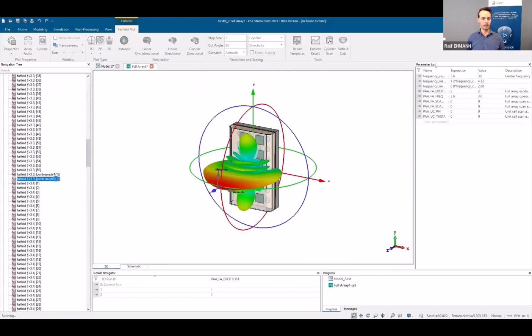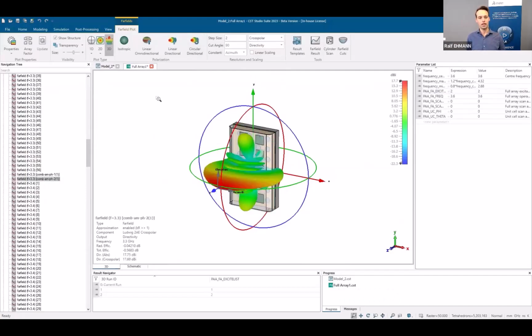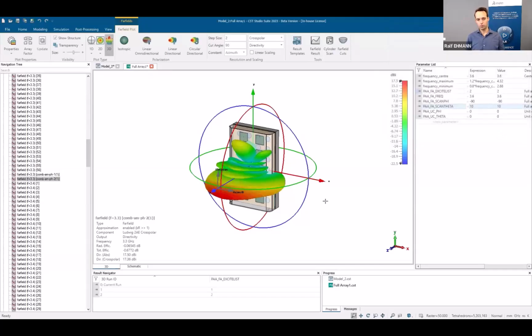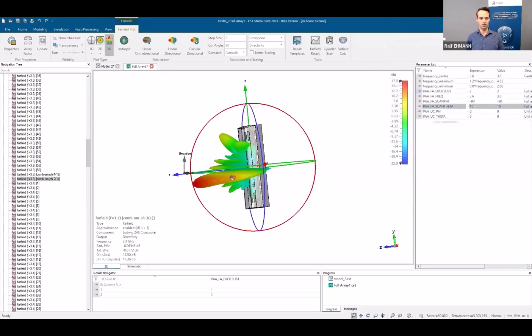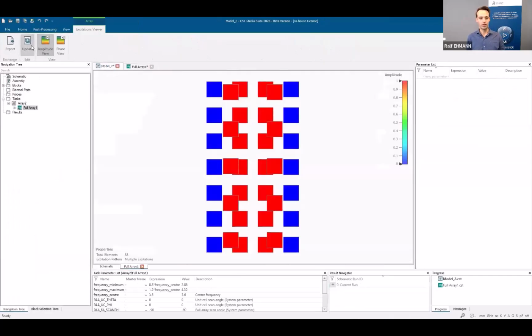You can also see then the cross-pol and the co-pol there, because as I said, it's a dual linear array. And you can see then I can even apply scanning on top of this. So basically I update it, and you can see the tilt that was specified, and so the phase calculation is automatically done in the background and adopted by this array simulation.